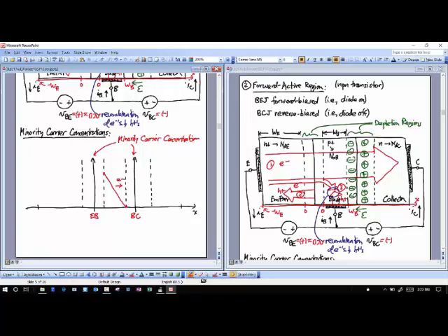The other base current component that happens is because if I'm going to forward bias this base emitter junction, then that means I'm going to get a hole current. I'm going to inject holes to the emitter side as well, which is going to create a current, and that's base current. That's both emitter current and base current. So current number 2 here contributes to both emitter and base current. I don't like that because that's base current. I want my base current to be as small as possible.